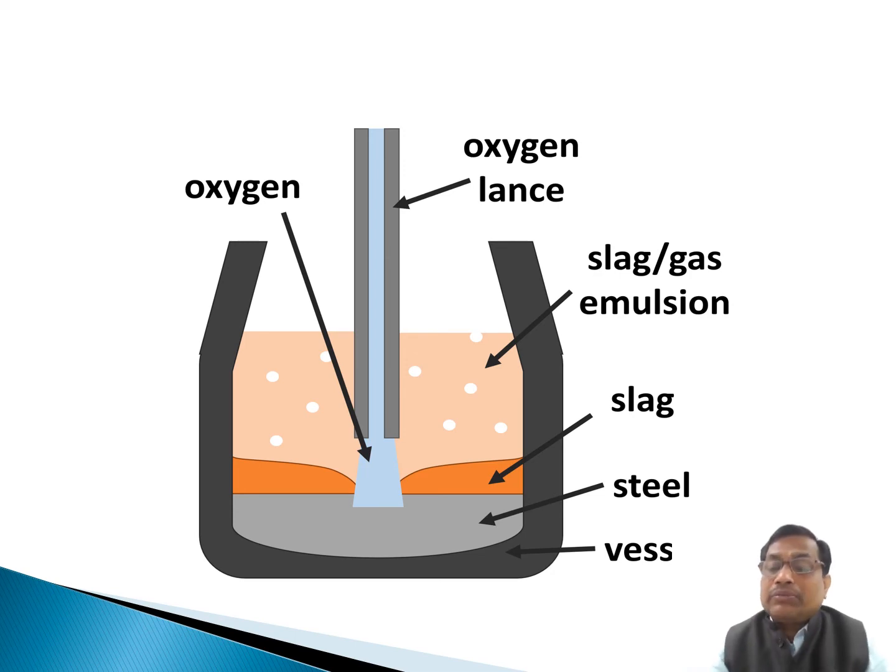So what is the structure of the ingot? An ingot is just like a brick structure, a rectangular block. That solidified block will be sent to a hot rolling mill, where we can press the ingot to convert it into a steel slab, or plate, foil, strip, whatever the requirement is. Also long products like channels, bars, solid cylindrical bars, and square section bars can all be produced from this ingot. So the preliminary step for this steel is the ingot.